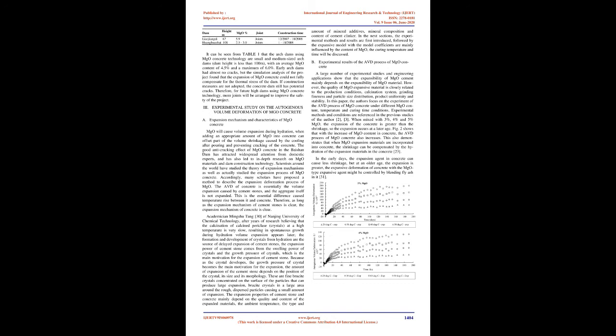The Changsha Arch Dam used 3.5 to 4.5% MgO in the entire dam section, compensating for thermal stress during construction by using its expansion characteristics. This method simplifies the prevention of concrete cracking compared with traditional concrete pouring methods such as ice cooling. 27.